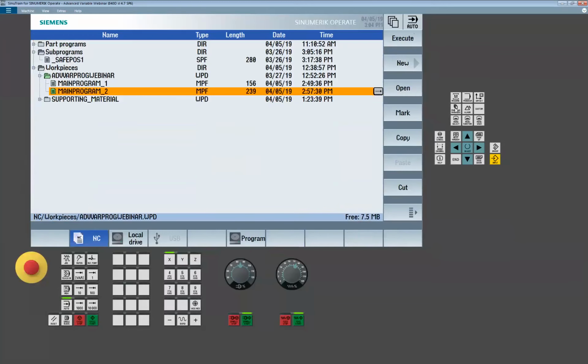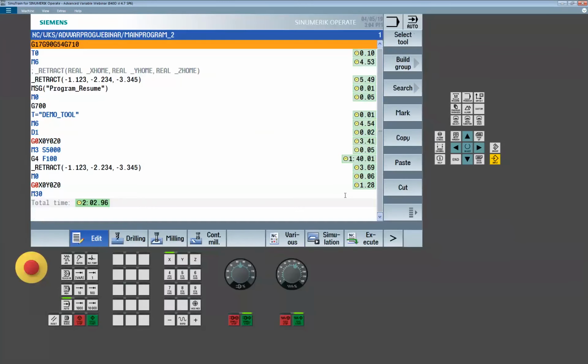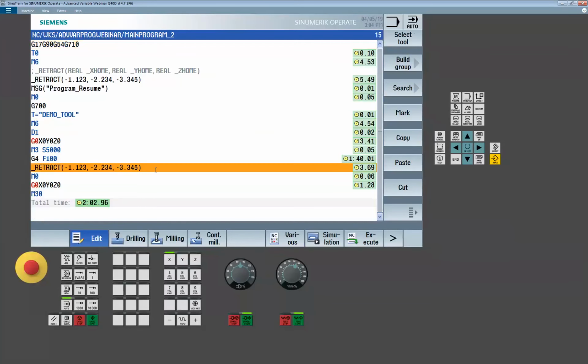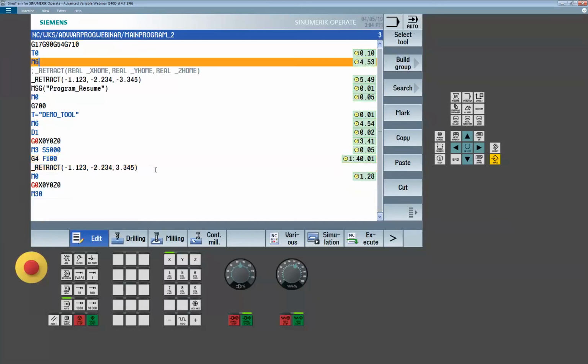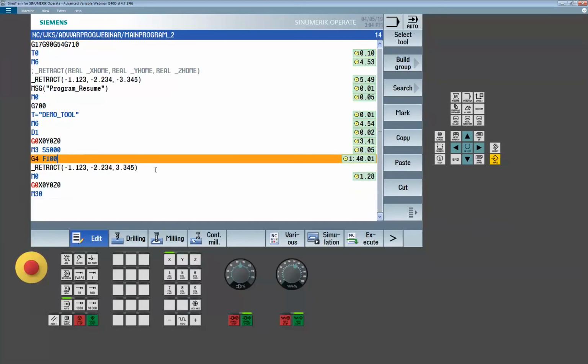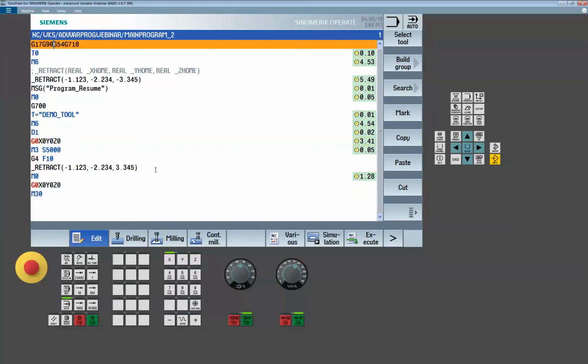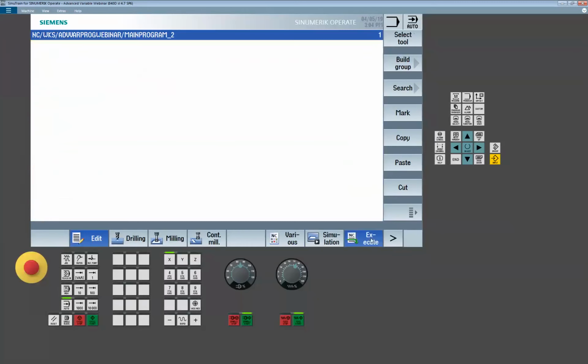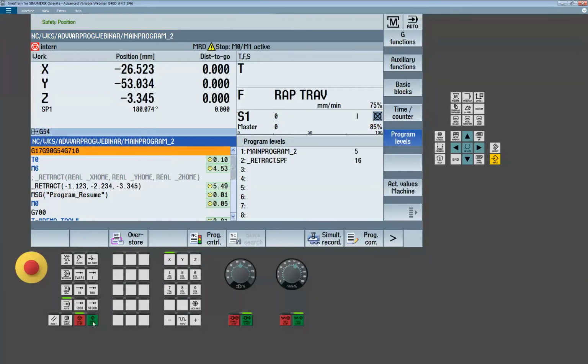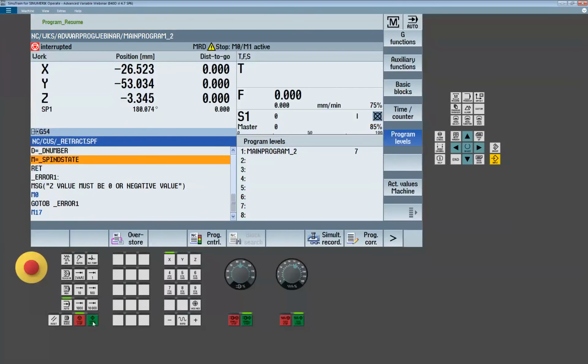Okay. So I didn't change anything in the PROC, so I don't need to reboot. So now I can come into my program, and my first one's okay, but I'm going to make my second one no good. All right, and I'm going to reduce this dwell. It'll be a lot quicker. Okay, so we go to execute. We run, safe position. I'm going to let it bounce back. It's back in the main program. You see we're back to the main program.